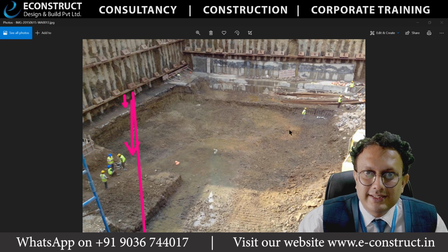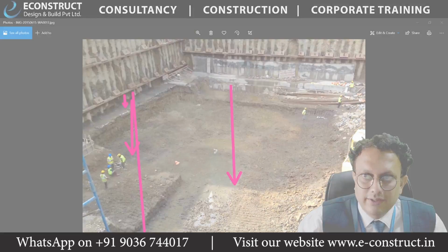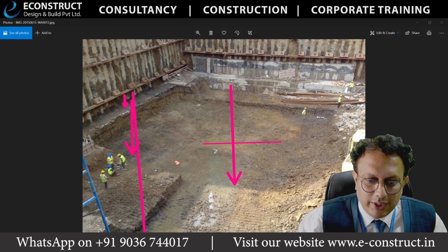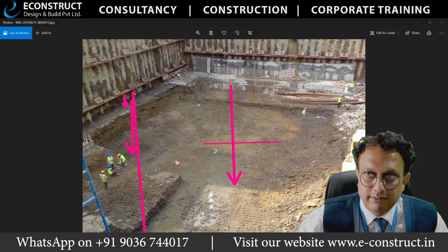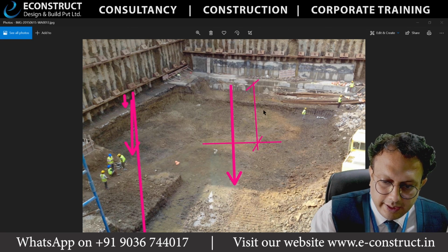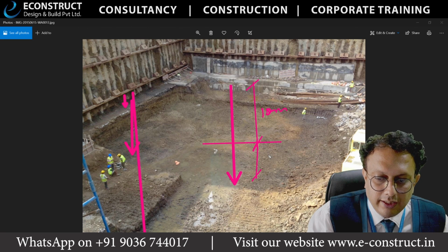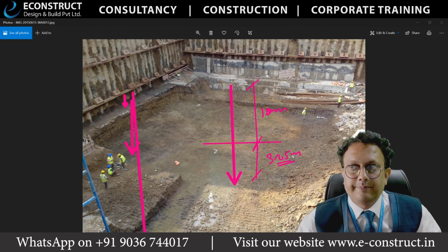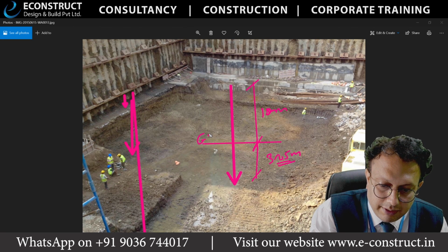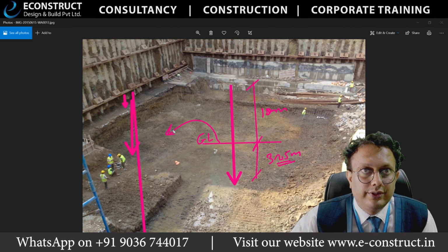How much is the distance? If this is the pile, which is going down, generally this distance should be 1/3 of this. Minimum 1/3 to 1/2. If this is, let's say for example, 10 meters, how much should this one be? Between, let's say, 3 to 5 meters below GL, the ground level. Understood? Okay.